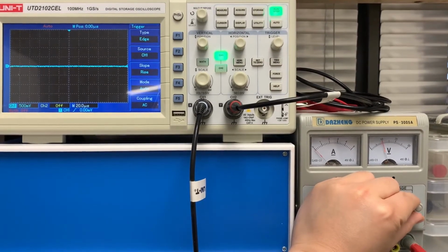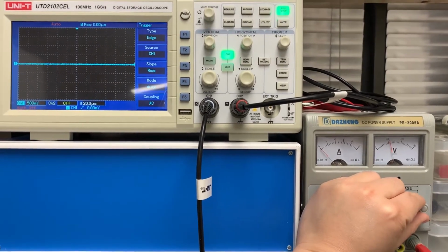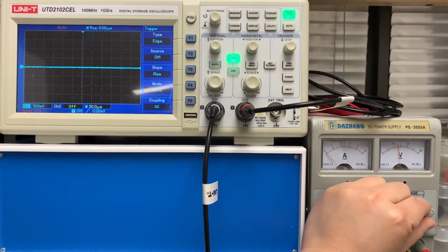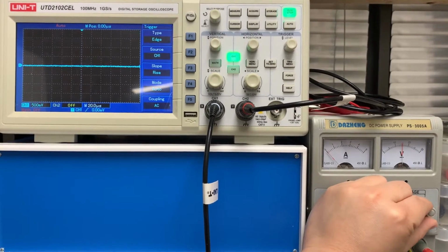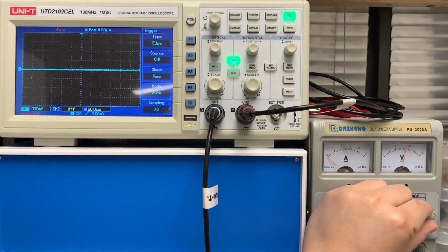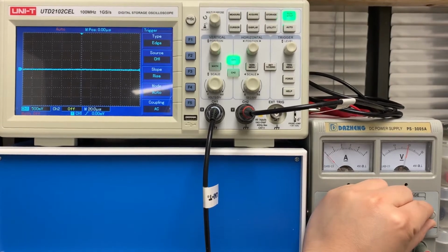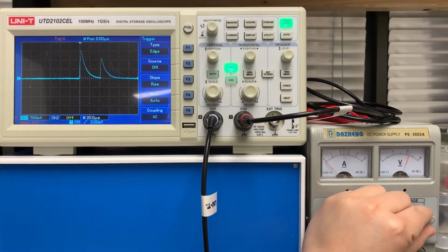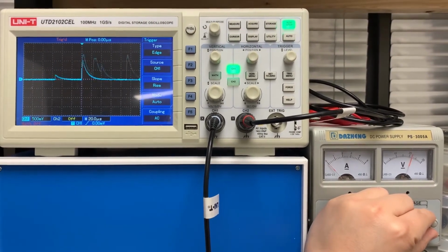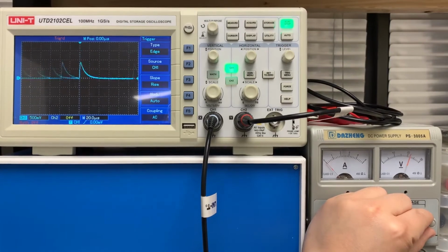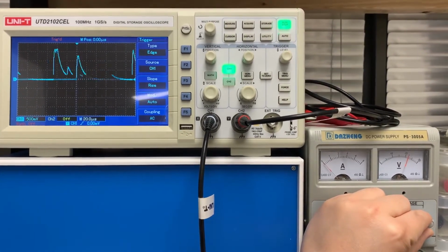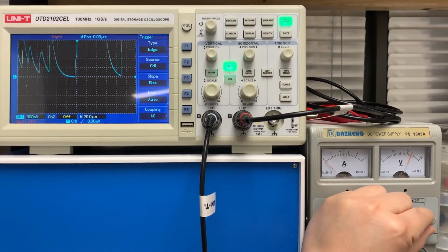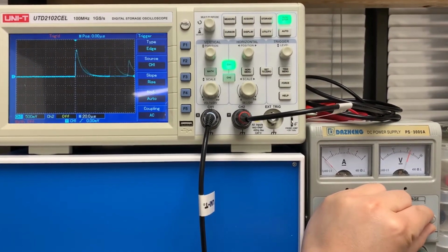Let's see. So now by going to 10-20 volt, it actually won't burn out the LED because we're in the breakdown region of the LED, so nothing is going to catch fire or smoke or anything. So let me just slowly increase this. Slowly increase it, and okay, so now we can see there's some avalanche current action going on in the oscilloscope now. Okay, if I keep going with the voltage, it's going to go crazy. So now let's just go back to something that is nice and clean.